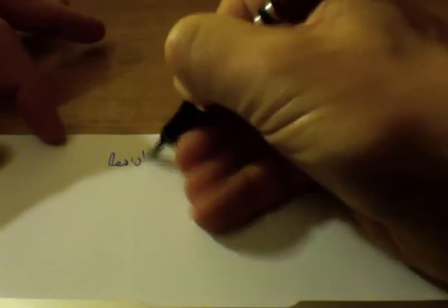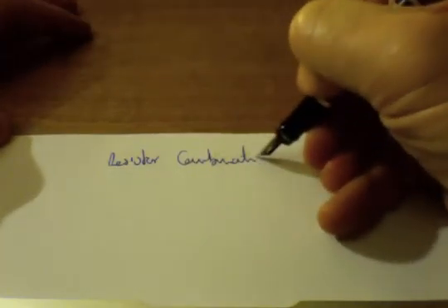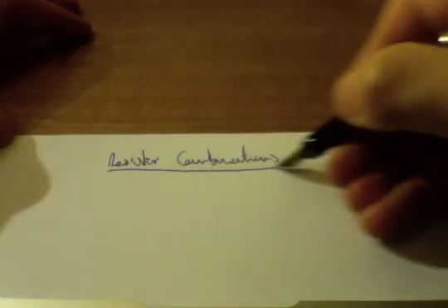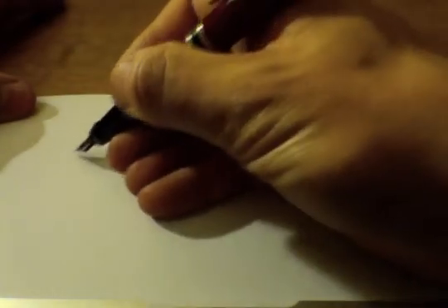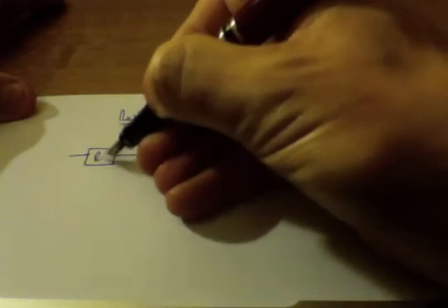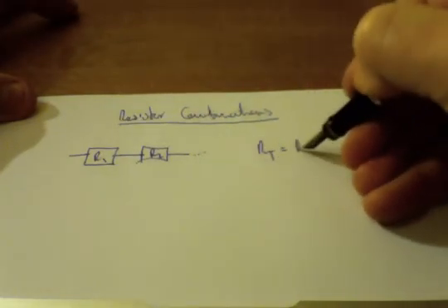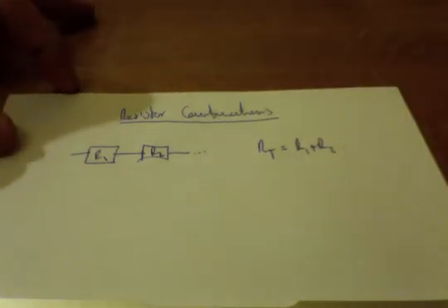Lastly, I will just show you how we do resistor networks or resistor combinations. This can be very straightforward. Once again, a little bit of maths here. We can prove it with Kirchhoff's law later. I'll just show you briefly how we put them in series with each other. R1, R2. Our total resistance is R1 plus R2. I'm sure you're aware of that one. That's the easy one, and as many as you want to add.